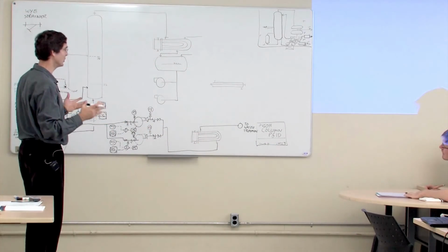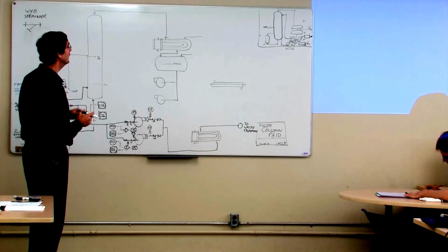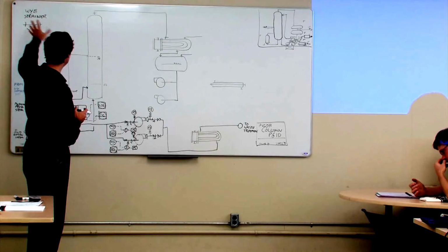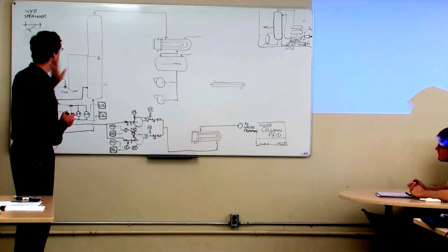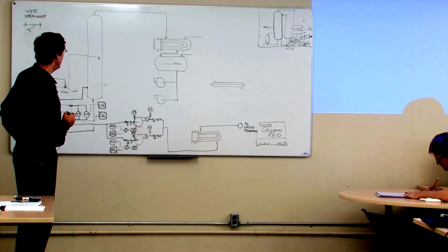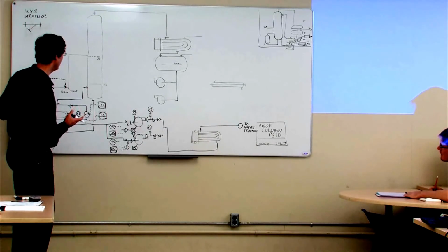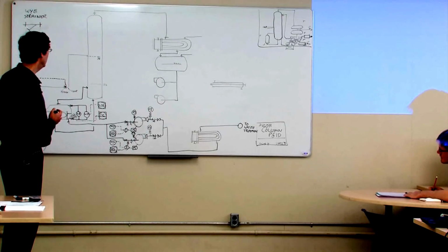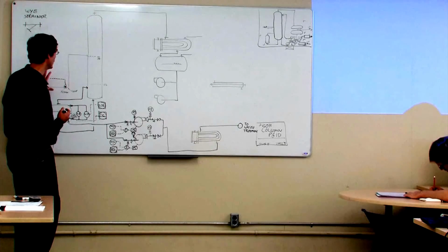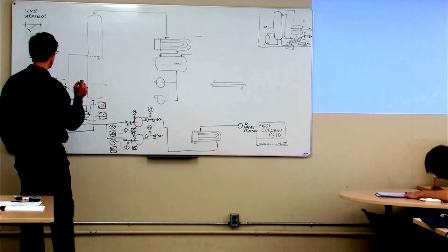It made sense because that's how the instrumentation was actually run in the field. It was all pneumatic instrumentation. It was really kind of neat because you have all the instrumentation up there, and all the process equipment down at the bottom. Unfortunately, well, not unfortunately, but the ISA came along and said we want to do it more with this style where we show the controllers closer to the equipment. So the history was that DuPont lost that discussion, and now the convention is to do it this way. But it's neat to see those old P&IDs.